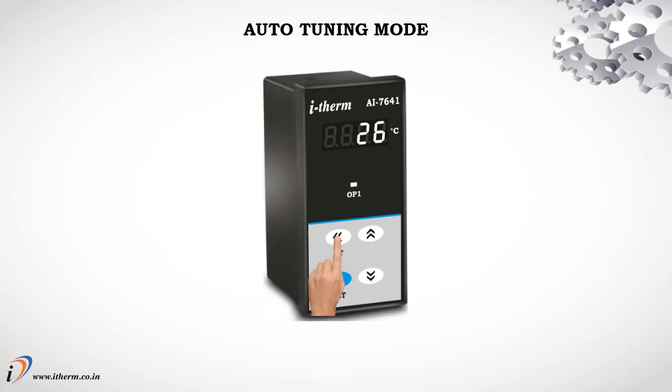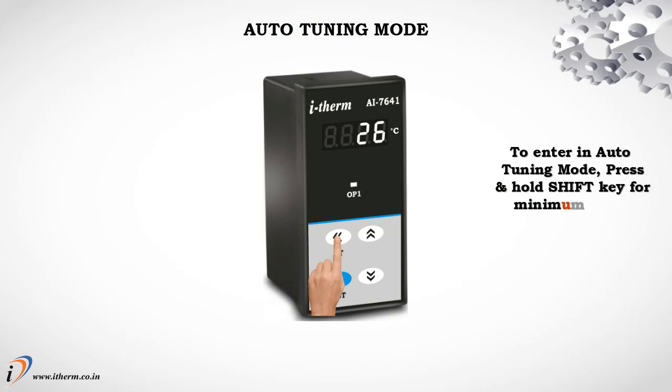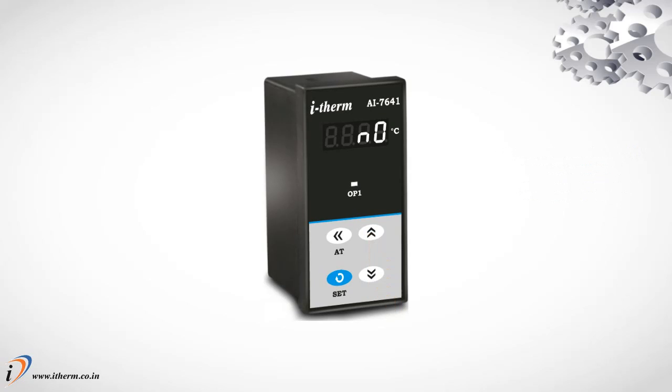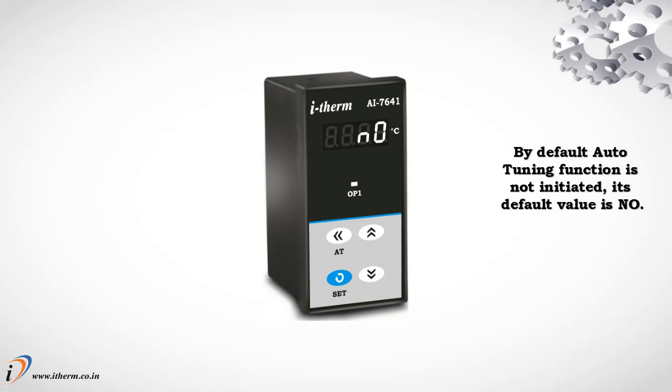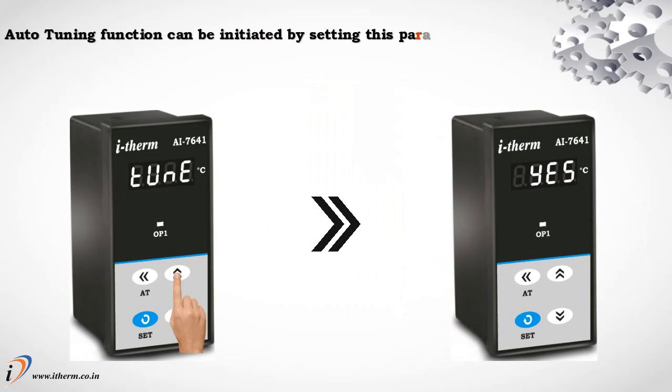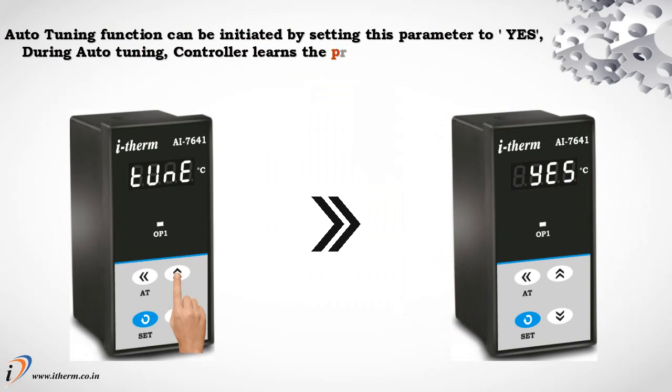Auto-tuning mode. To enter auto-tuning mode, press and hold the shift key for a minimum of 3 seconds. This parameter will appear only if the selected control action is PID. By default, the auto-tuning function is not initiated. Its default value is no. The auto-tuning function can be initiated by setting this parameter to yes.